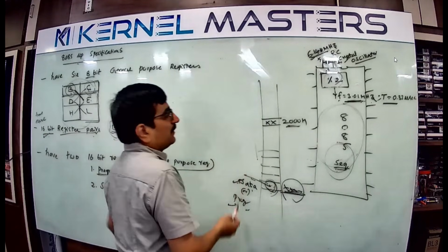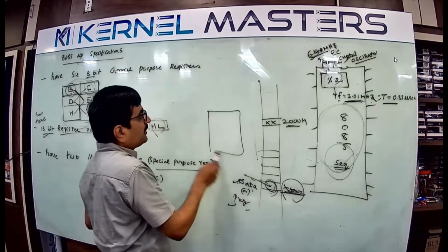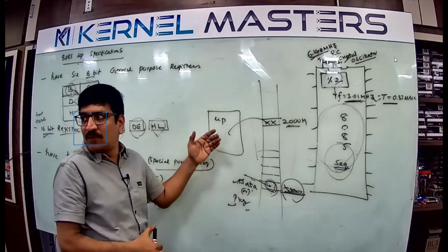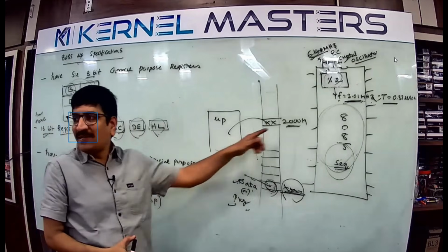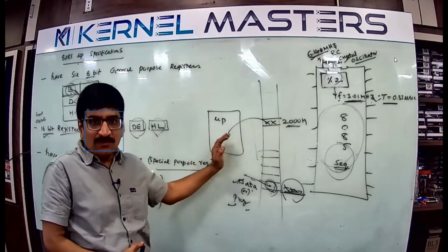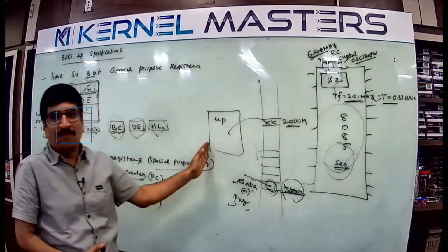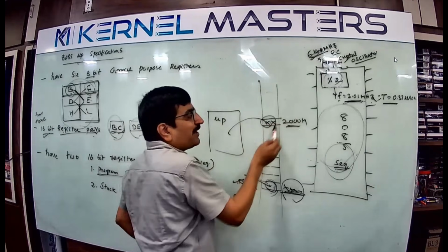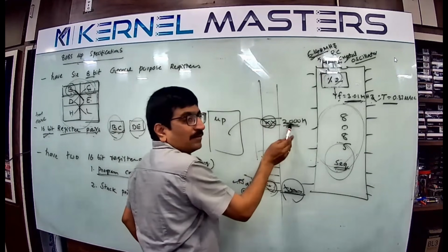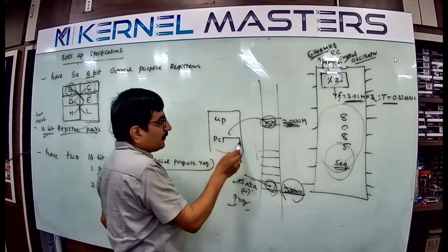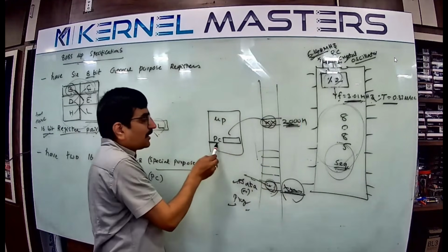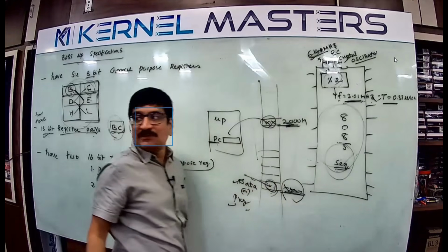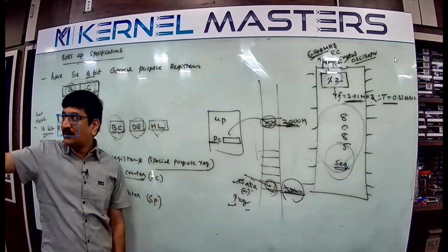So is it the microprocessor's responsibility to load the program or not? What is the microprocessor's goal? Execution of a program. But where is the program located? In memory. So the microprocessor communicates with the memory and loads the program, but it should know where the program is located. That address is given to which register? The program counter. The program counter holds the address of the instruction, where the program is in RAM.